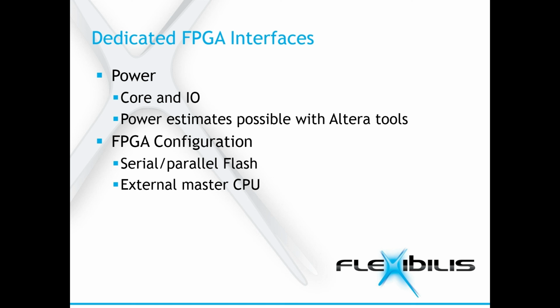In this case, the bit stream can be located in the same flash memory as the software of the CPU. This may bring savings in the hardware cost because this will result in one less memory chip on the printed circuit board.